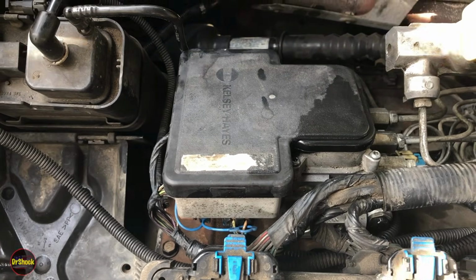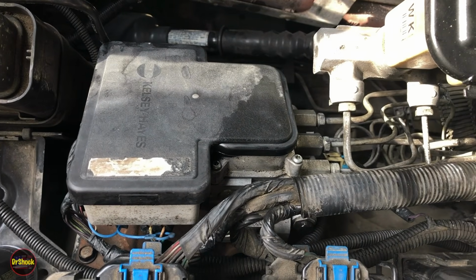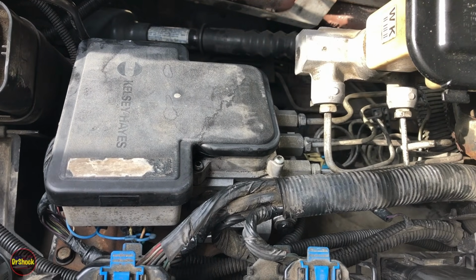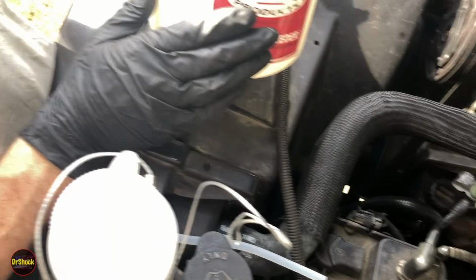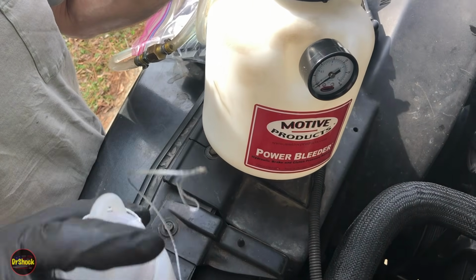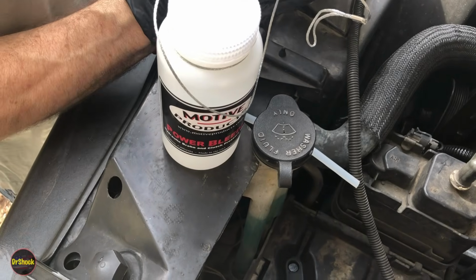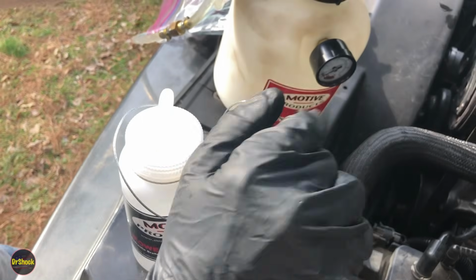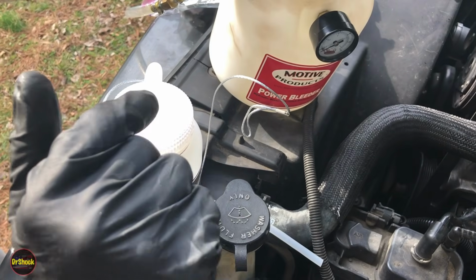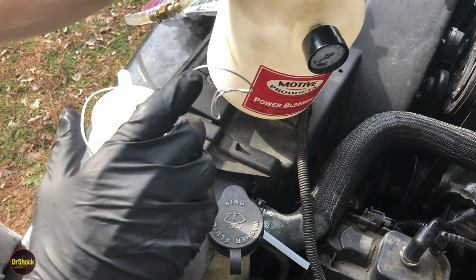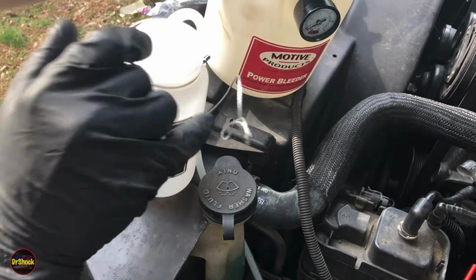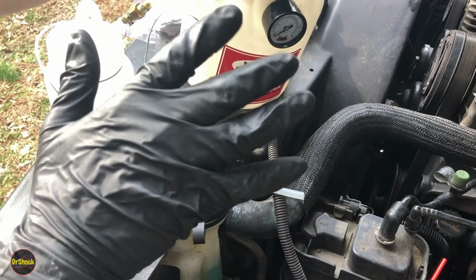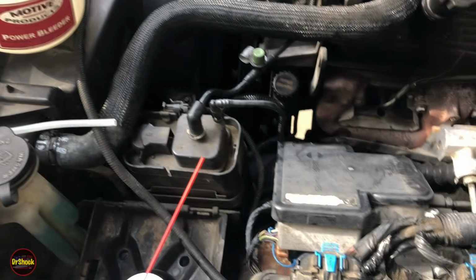And then the next thing we're going to do is bleed the brakes, and then we're going to use the Tech2 to do a power bleed of the BPMV. So I'm going to be using a Motive power bleeder and a one-handed deal, so I can hook these up to each of the wheel cylinders in the back and the calipers in the front. I've already shown this in a previous video, so I will link that up in the upper right here, and you can watch that other video if you want to see how to use a Motive power bleeder and how to use the Tech2 to initiate the internal bleed of the BPMV. We're going to do that, we're going to come back, and we're going to take it for a test drive and see if we fixed this.